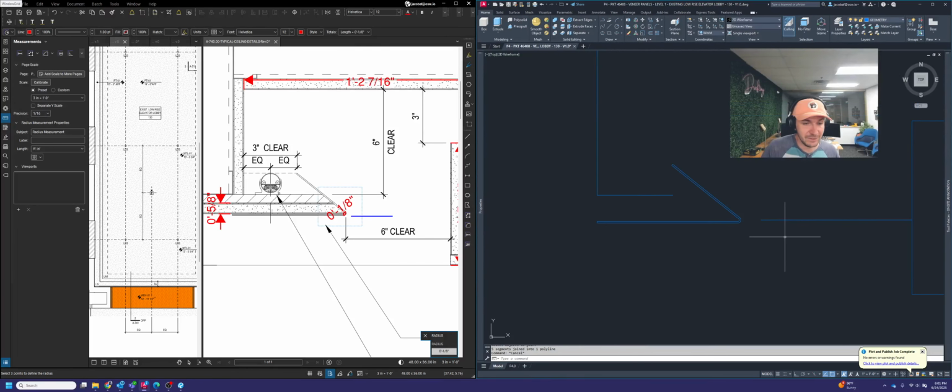Join and join. Perfect. One thing that I did notice is that although this is a 39-degree angle, my 6-inch dimension is still slightly off. So I think what I need to do is find out, if this wasn't radius, where would these 2 points meet for starters? So right there where those 2 points meet. And then I'm going to use the stretch command to shrink this light cove so that it's perfectly 6 inches here, like what's drawn here. So, recapping on the stretch command, again, it's a tough one to learn. Don't kick yourself too hard if you don't get it right away.